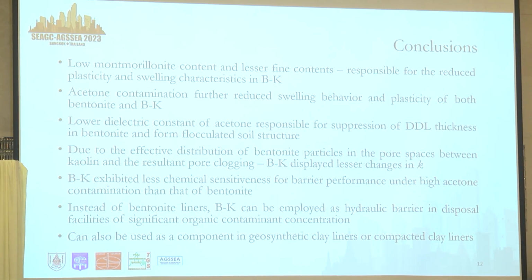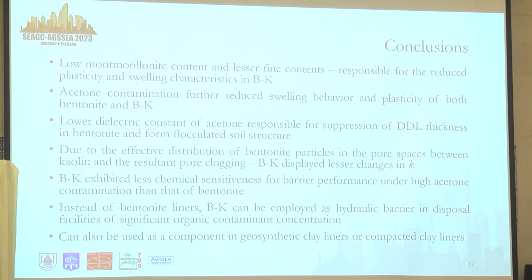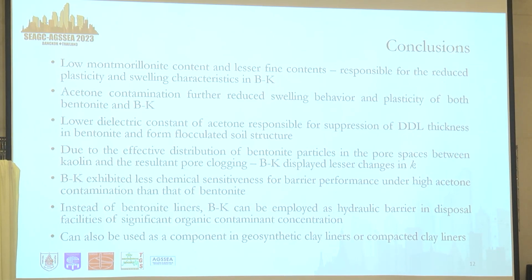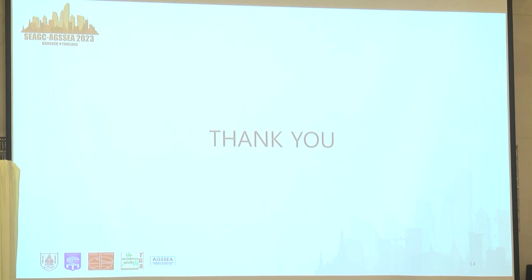We can say that BK is having a better chemical insensitiveness, and instead of bentonite liners, we can use BK mixtures as a hydraulic barrier in disposal facilities where significant acetone concentrations can be found. And it can also be used as a component in geosynthetic clay liners or compacted clay liners as well. So these are some of the references, and thank you.